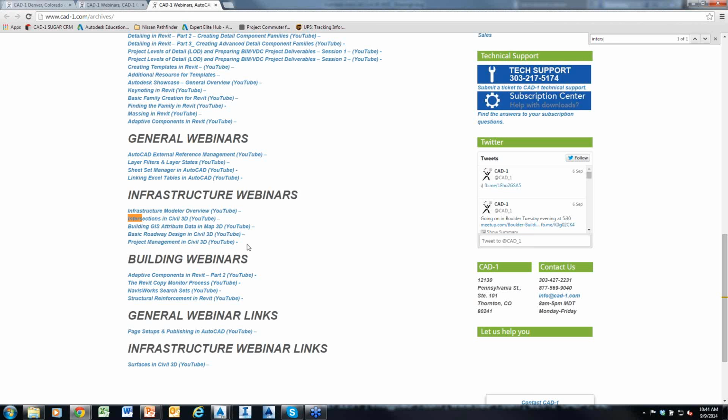Sheldon does ask, will this type of corridor match the gutter line alignment at the intersections? It depends upon how you're going to have to create multiple cross-sections or assemblies for your different intersections. How you set up those different assemblies will control whether or not it works. A lot of times in intersections, you're going to create assemblies specifically for your gutter flow line, so it should work.